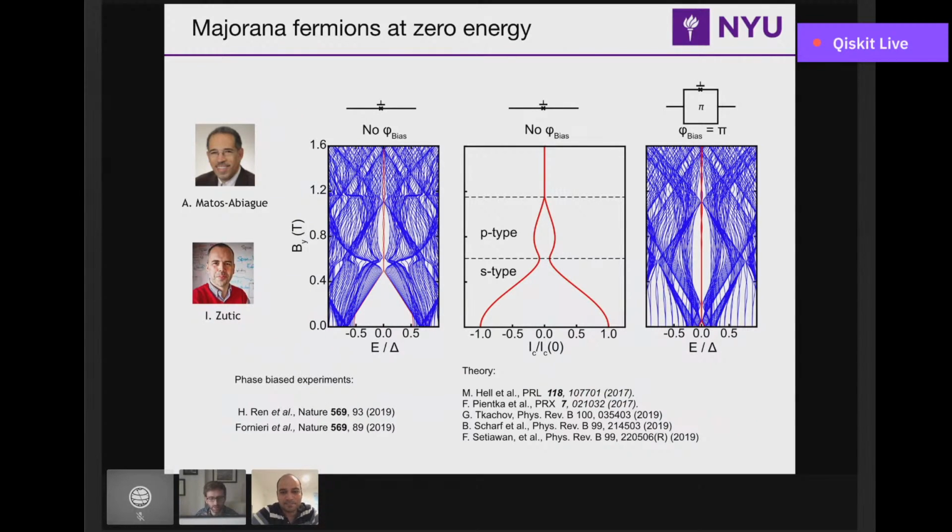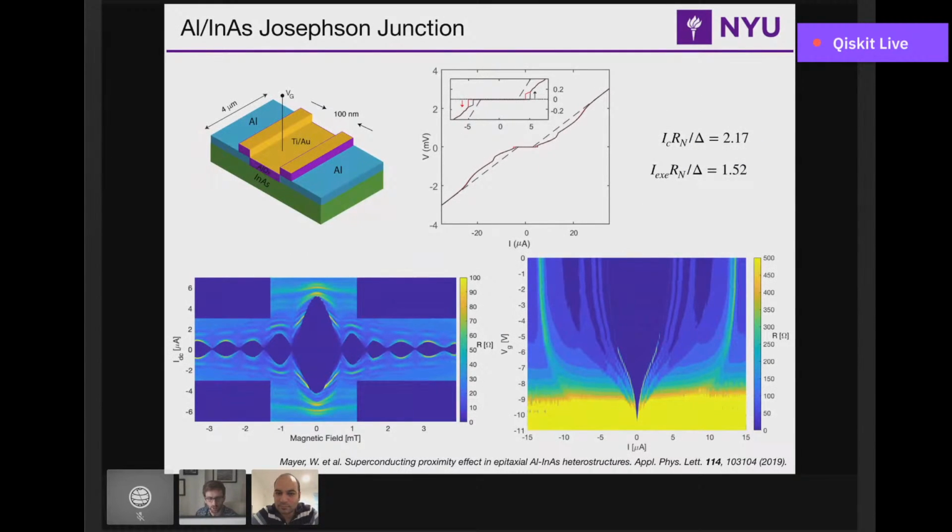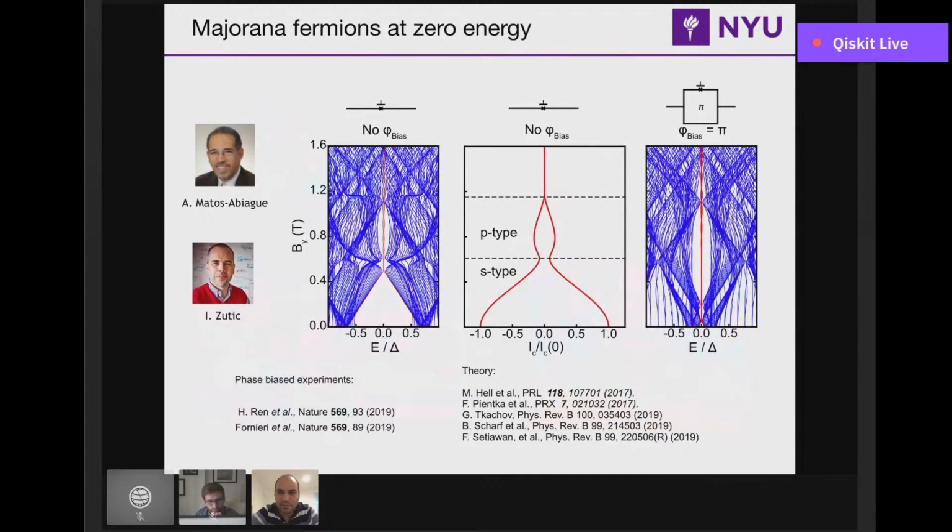Yeah, I was about to say, can you remind us what the voltage is defined between? When you say gate voltage, it's between which two? It's basically the titanium-gold on the top and the 2DEG. The chip, yeah. So it's practically a parallel-plate capacitor.